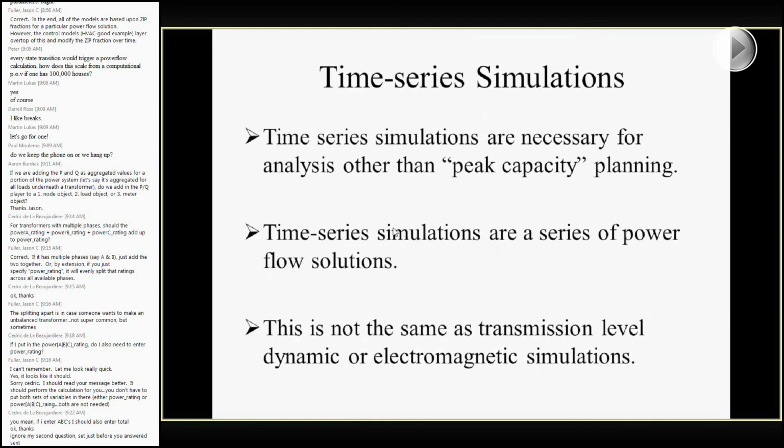So time series simulations is basically where all of the really useful things come out of GridLAB-D. Just as a static power flow solver, it is useful, but the big advantage of GridLAB-D, on the whole, is the time series simulations. If you want to look at how a house behaves with varying voltage, or if you want to look at system behavior over the entire day, obviously you just want to do some form of time evolution of those, or how the system will react to particular conditions. You don't want to just do one static power flow and say, yep, this is the answer, I'll derive everything from there.